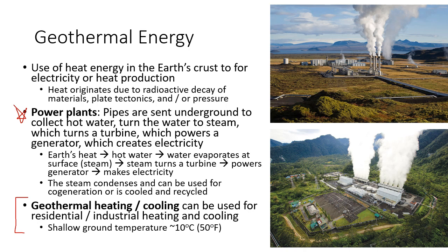We're talking like maybe 10, 15, 20 feet deep, and there's a constant steady state of about 50 degrees Fahrenheit, 10 degrees Celsius when you get down about 10, 15, 20 feet, depending on the location. Here in temperate Colorado, you have to go down maybe 10 feet, even less, maybe 5 feet. But if you send pipes down that far, you can push air through it, and that 50-degree air is going to come up and cool a house during summer or warm a house during winter.